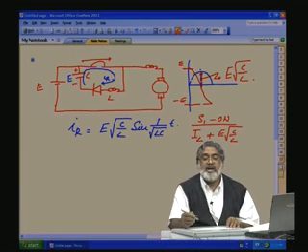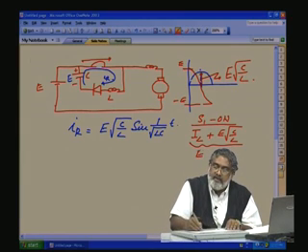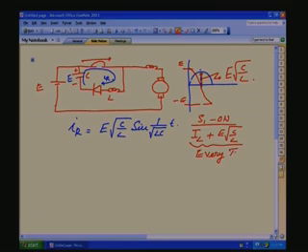This much peak current flows at every turn on. So, the maximum load current plus E into root C by L will go through the thyristor. This current, E into root C by L, is of small duration.